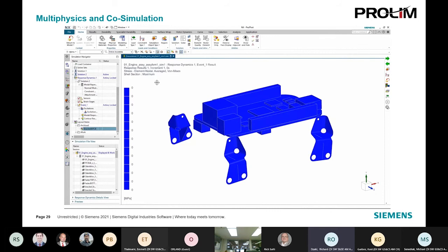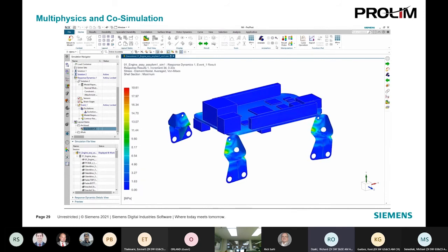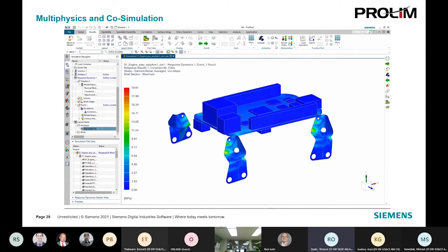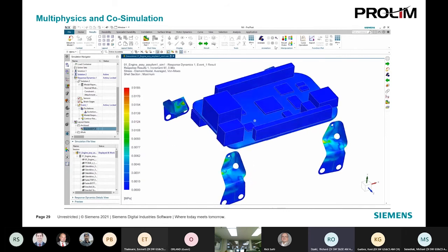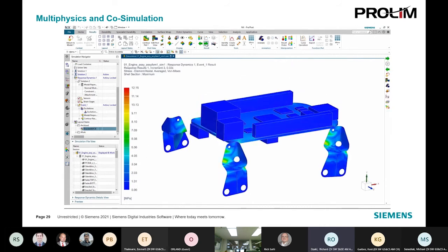After the solve, we can directly open the results on the same user interface and define post-processing activities. At this stage, we're able to define the mechanical stress on the bracket and the acceleration on electronics components. Transient von Mises stresses are predicted and shown in the support brackets in the PCB. The analysis identifies where the increased stresses are located so that remedial action can be taken.